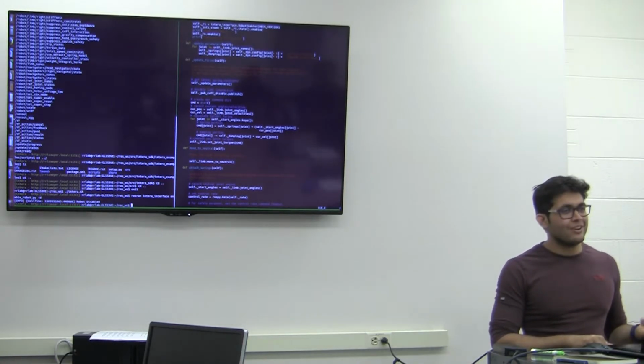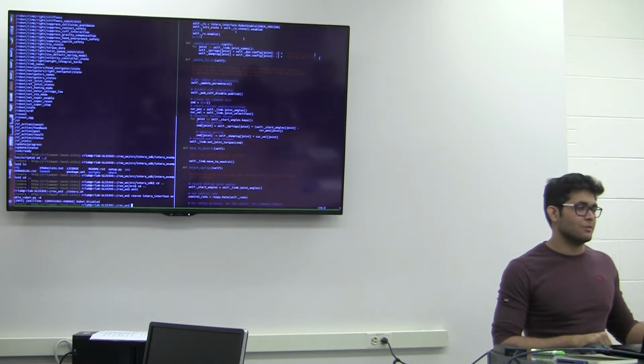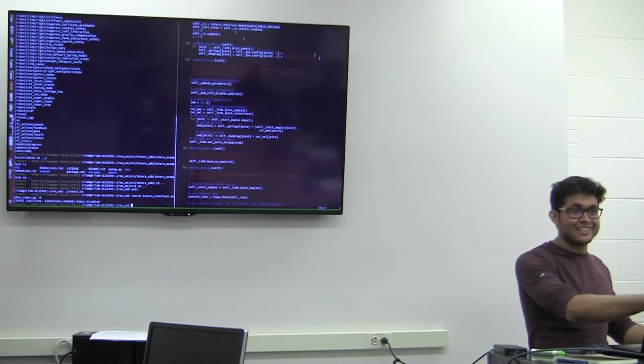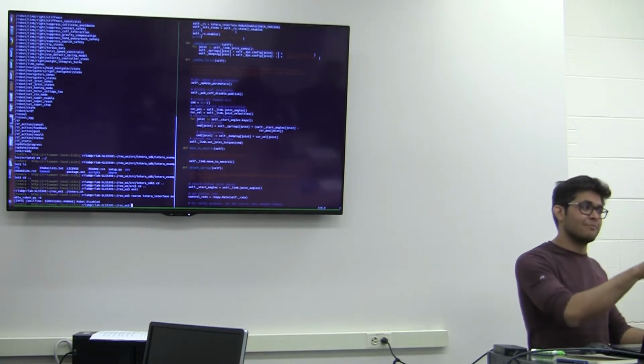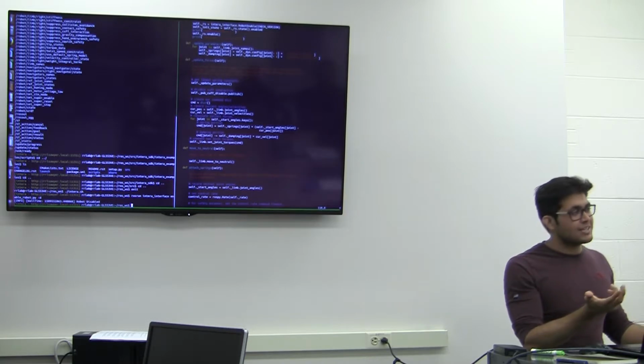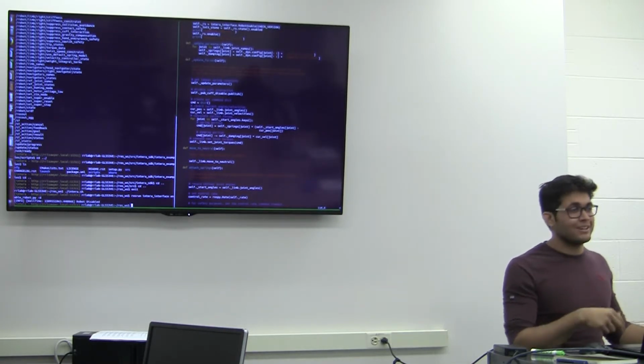It might not, but be safe and stop the robot there. Don't panic and hit Control C here. It doesn't matter if you hit Control C there, right? Sometimes the messages are published and the robot has already read those messages. If the dynamic server is smart enough, it might stop, but it might take a long time.